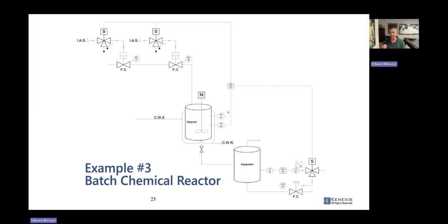So in order to get to a safe state, my core action is, if the temperature is high, stop feeding my reactor. If I stop feeding my reactor, the material will react, your reactant concentration will decrease, your reaction rate will decrease, the temperature will decrease. So in order to prevent the runaway reaction from occurring, all I need to do is close one out of these two valves.